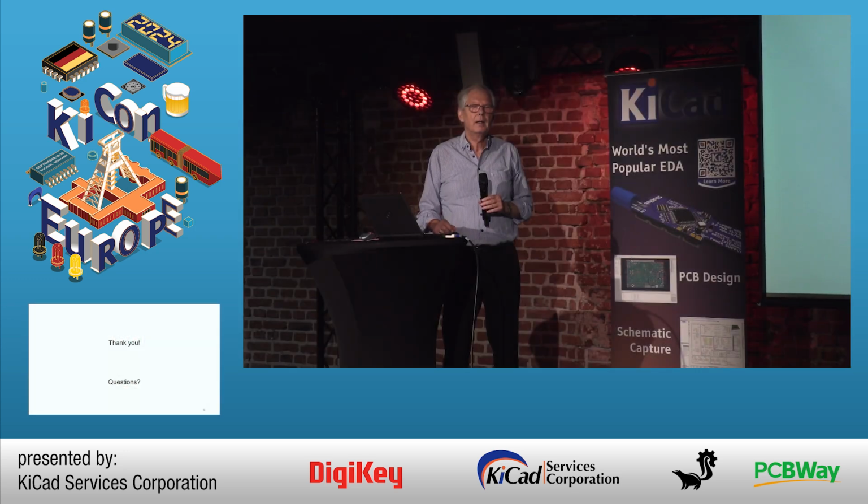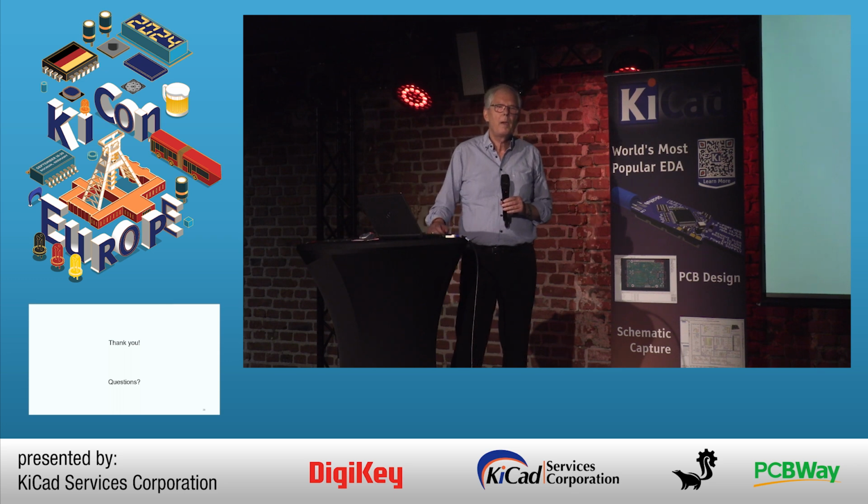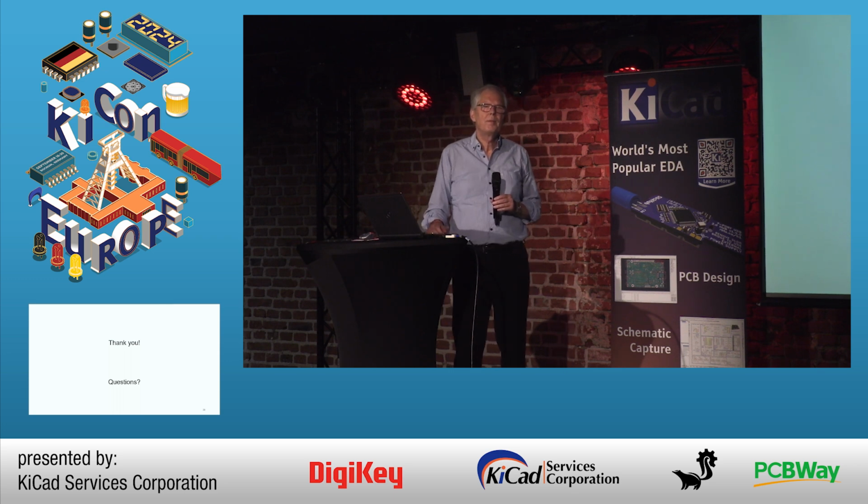Hi. I'm working with circuits of quite high frequencies, and I was wondering, when it comes to ngspice implementations and those calculations on non-linear equations, is there any limit on frequencies over which we should be concerned about numerical errors inside the simulation engine?